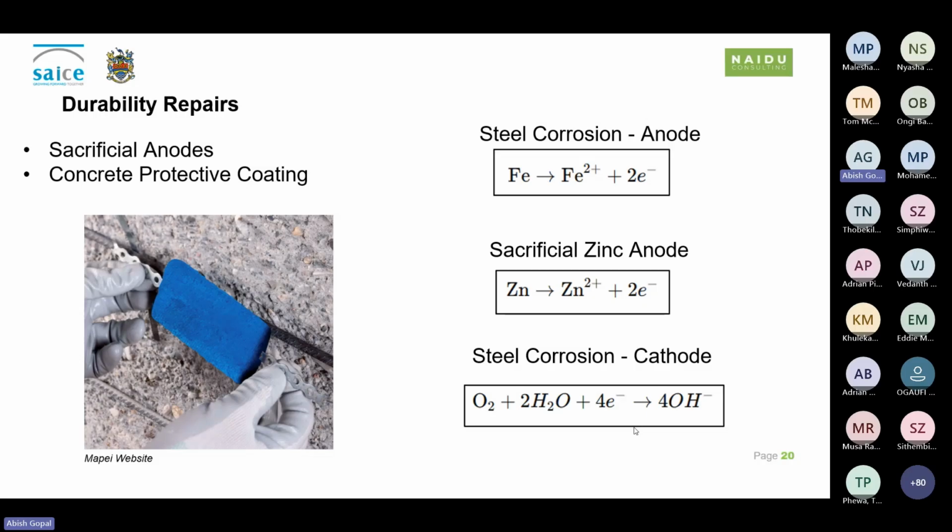The reinforcement steel now becoming the cathode is more resilient, and thus breaking down the anode, which is now our sacrificial metal. So in this instance, we are protecting our steel and promoting a much more durable structure. This approach was specified for all spall repairs in the bridge, specifically due to the location of the bridge being at the ocean. This served as best practice to reinstate the durability of the structure.